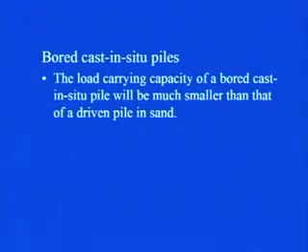Now, this was all about the driven piles. Let us see some of the salient features of bored cast in situ piles and how we can estimate point bearing resistance and skin friction resistance in case of bored cast in situ piles. The load carrying capacity of a bored cast in situ pile will be much smaller than that of driven piles in sand, because in case of bored piles a void is created and then the concreting is done.